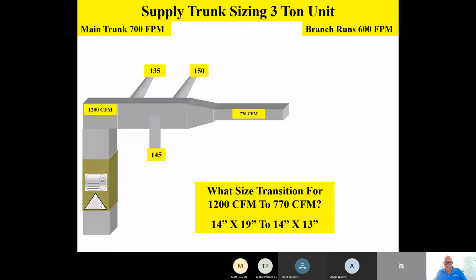So in this next section of duct, we've got 770 CFM at 700 feet a minute velocity. And now let's go ahead and start taking off some more takeoffs here for the next sections in our conditioned space. So in this next section here, we've got 90 CFM. Maybe it's going to a small room or maybe a large closet or something like that.